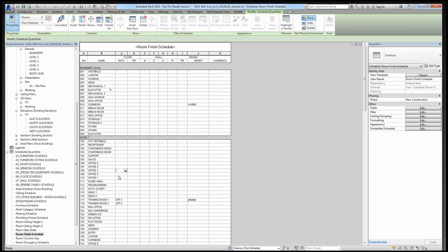And if I needed to, say, for each of my walls have a similar finish on each of the 4 walls in a particular room, I can't just autofill across very easily. I have to manually copy and paste values and manually click into individual cells. I can't hit enter or use my arrow keys. So it's not Excel. It's still obviously editing back to the original room, but it doesn't have quite the functionality that Excel has. So what I'm going to do is take this exact schedule and kick it out to Excel so I can more easily edit it.